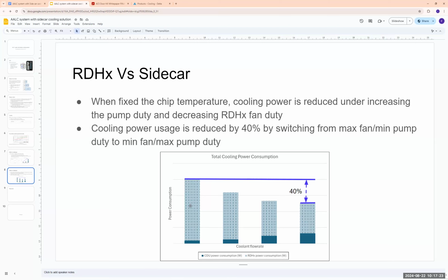They are only using adiabatic cooling and nothing. Yeah, but in my opinion, what I thought is in a radial heat exchanger, you have air supplied from the chillers or the cryonets come to the hardware, and then that will cool the hardware peripherals, and then it will cool the liquid from the radial heat exchanger, and after that it will release the hot air into the hot aisle.